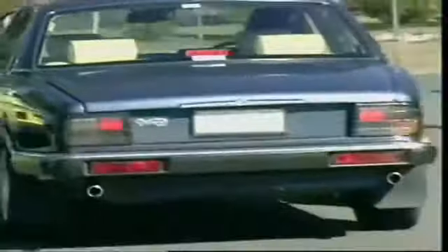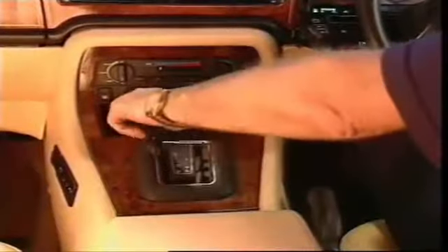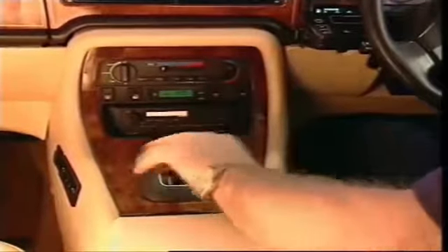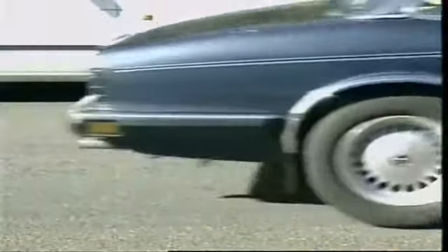An automatic transmission or transaxle performs similar functions to a manual transmission or transaxle, except that gear selection is controlled either hydraulically or electronically. The automatic transmission uses a torque converter, which acts as a hydraulic coupling to transfer the drive.